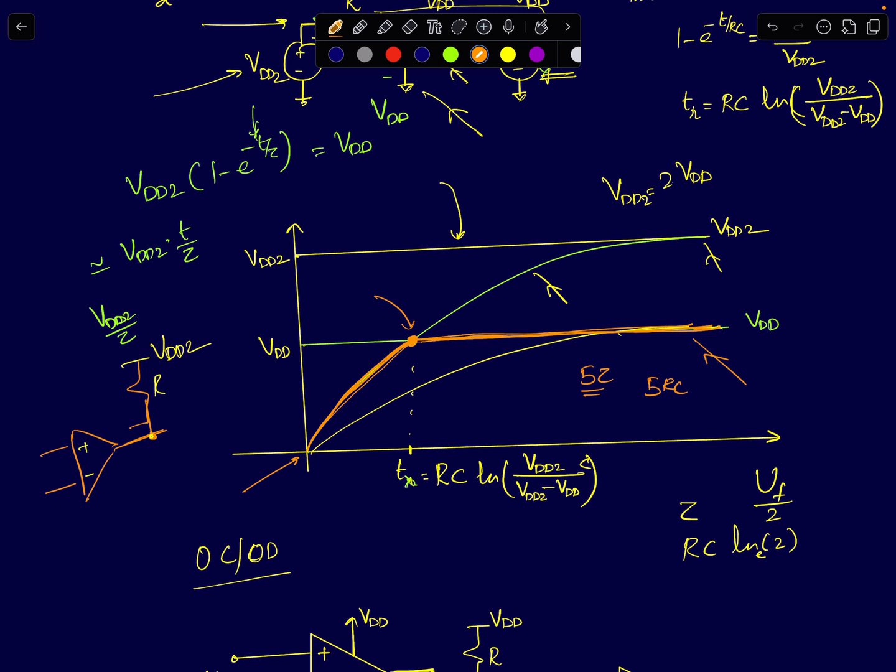Okay, so shown in yellow here. What does yellow represent? This represents the conventional first order charging, the normal first order charging using a simple RC circuit with a supply voltage of VDD. It would have taken much longer to reach VDD volts. It would have taken 5 time constants. It reaches the final voltage of VDD only at t equal to infinity. It tries to reach it asymptotically.